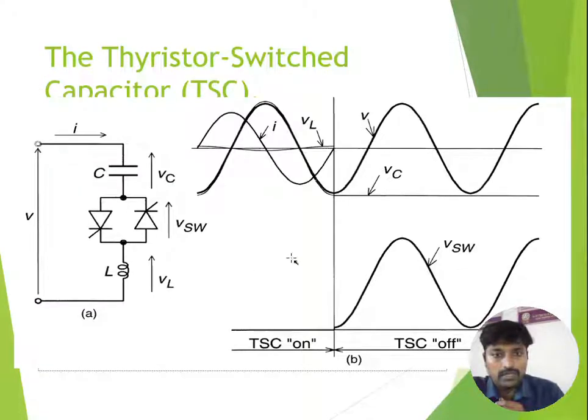Then you come to the thyristor switched capacitor. In the thyristor switched capacitor, you can clearly see that anti-parallel thyristors are connected in series with the capacitor. A small inductor is there to avoid sudden changes, for safety purposes, simply protection.